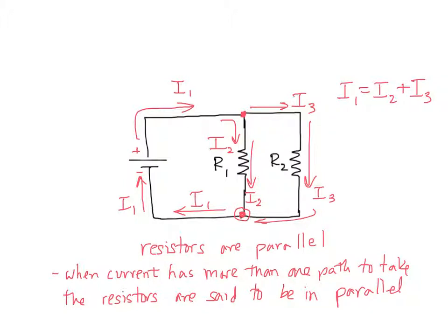Basically, it's like opening a switch so that there is not a closed loop anymore and the current won't flow through the circuit anymore. Obviously, you have to have a closed loop in the circuit for the current to flow, for the charge to come back in the negative terminal of the battery to keep flowing through the circuit. If you broke this circuit anywhere, so if you just cut this wire right here, now you don't have any flow anywhere in the system because you don't have a closed loop. That's what a circuit breaker does. So that's why we want to size this wire. We want to know how much current is going through each individual branch. So I'm going to teach you how to determine that in the next couple slides.